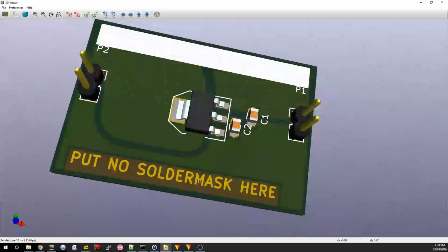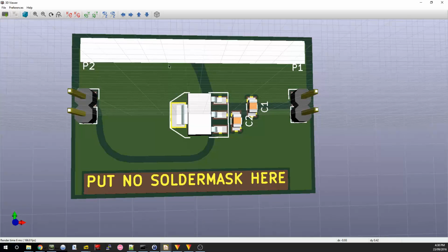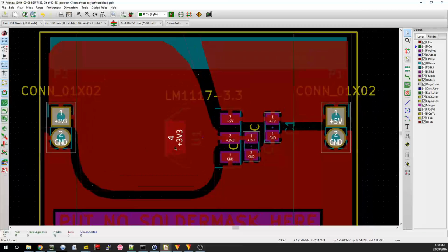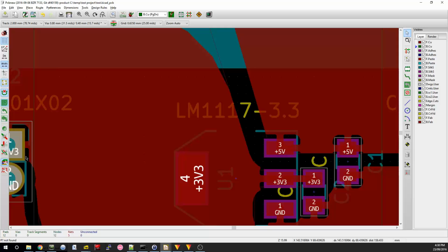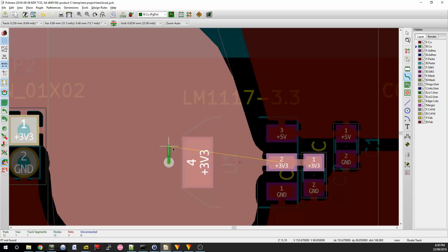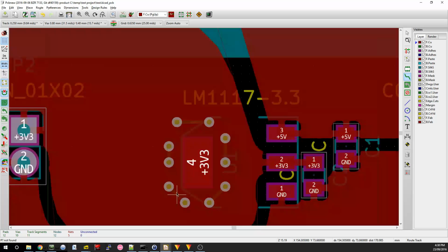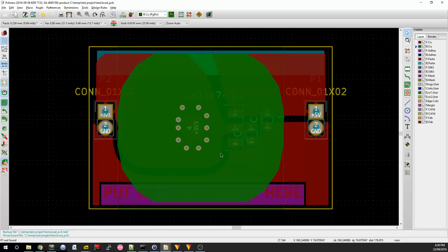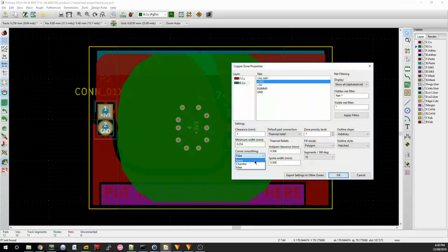If we look at the 3D viewer, it's more obvious that there's no holes in the center area. There's holes on the side, but I haven't made the plane extend that far. So what you need to do is either add some vias or add some through-hole things. So to do that, let's do this. I'm not sure if this is the correct way to do it, but works. So you definitely need some sort of connection to the bottom. And once there is any sort of connection to the bottom, it will fill the bottom area. This really should not be...